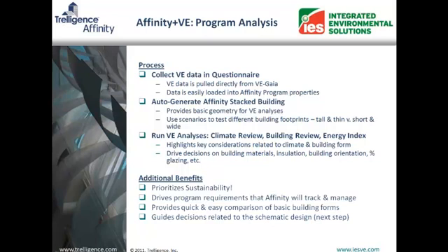With the program and VE data entered, we can generate the stacked building to provide some geometry for VE to analyze. The generate stacking script can also be rerun with different story areas to create a variety of tall or short buildings that can be compared using the Affinity scenarios.